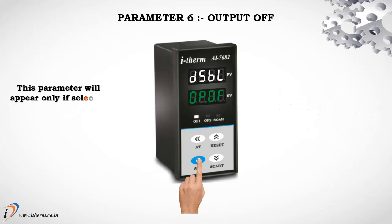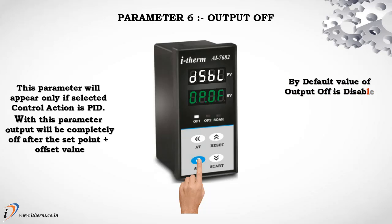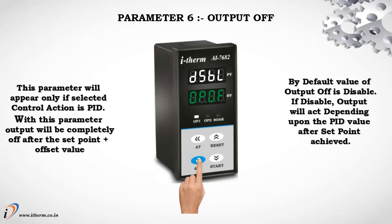Parameter 6, Output Off. This parameter will appear only if selected control action is PID. With this parameter, output will be completely off after the set point plus offset value. By default, value of output off is disable. If disable, output will act depending upon the PID value after set point achieved.